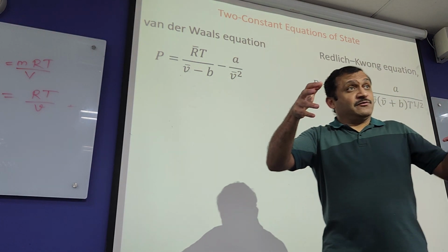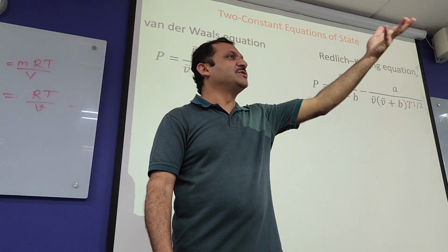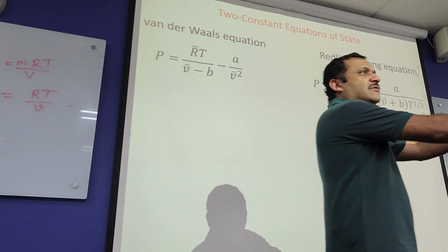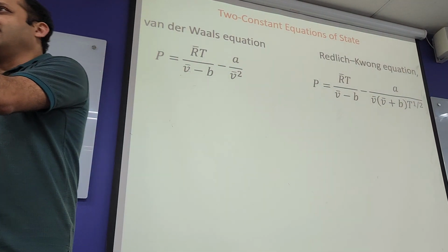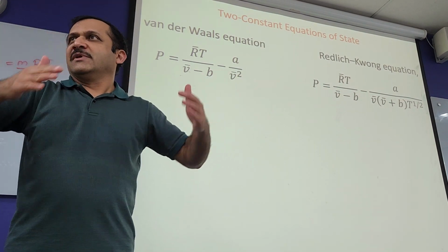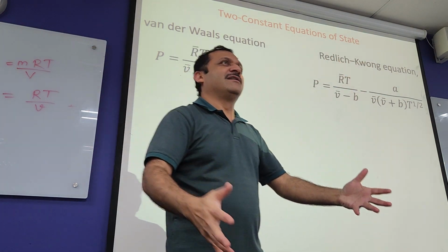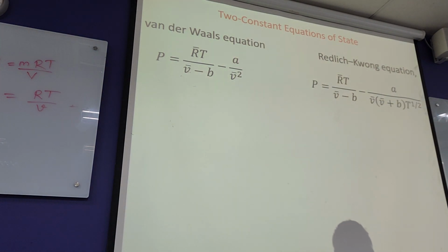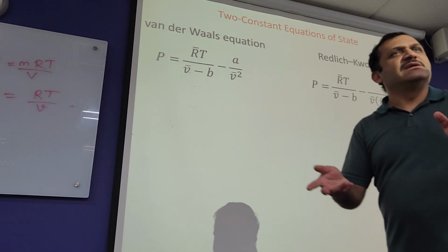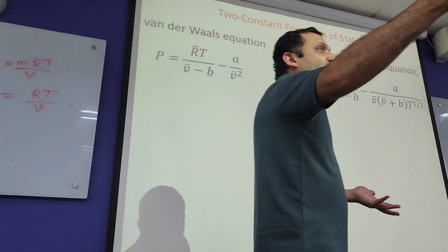But at the beginning, you have to estimate how much volume of air needs to be stored, and that will depend upon how much is the usage. So you have to estimate, okay, pneumatic tool 1 is using so many cubic meters of air every day. A lathe machine is using so much, an operator is using so much to clean, and so on. And then predict, in a day we need that much air. Now, you're going to estimate it most likely to begin with in kilograms of air. And kilograms of air doesn't matter whether you're on Earth or Moon, kilograms is kilograms. Volume though is different.